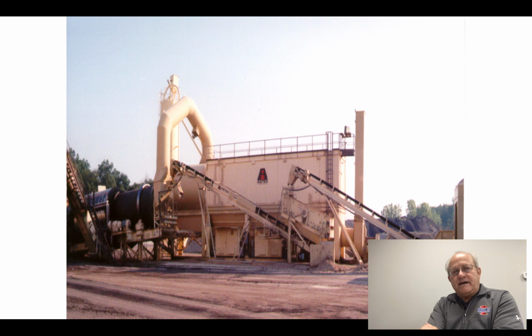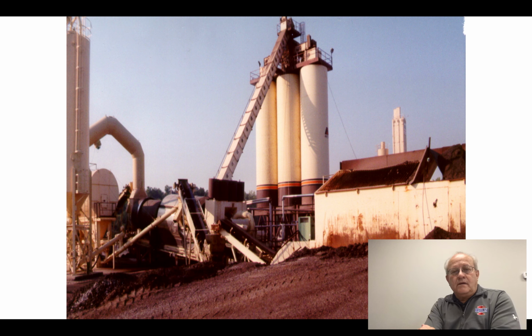Now the dust that comes out of the bag house goes right back into the mix. Sometimes you put it all back in, sometimes you don't. That gets back to where we were talking about calibrating the dust return system. Different view, these are the wrap feeders putting wrap into the other end of the drum where it mixes with the virgin aggregate. The dust silo on the left there with a screw conveyor, taking dust up into the drum, returning it back to the mix.